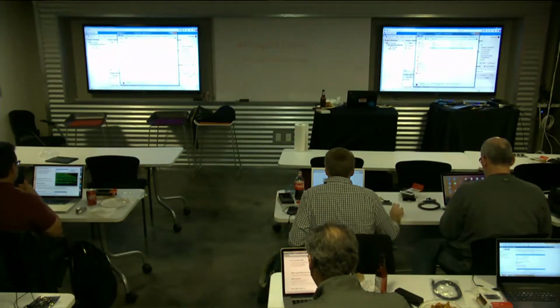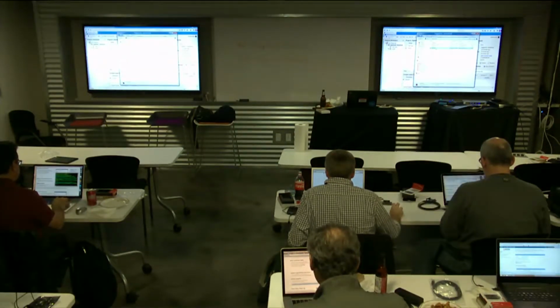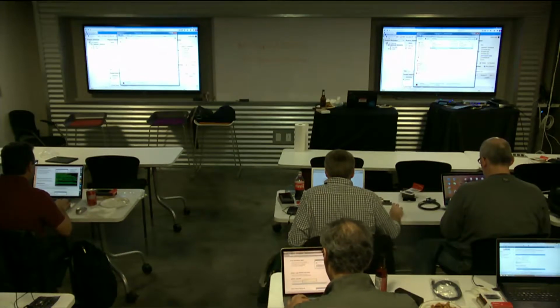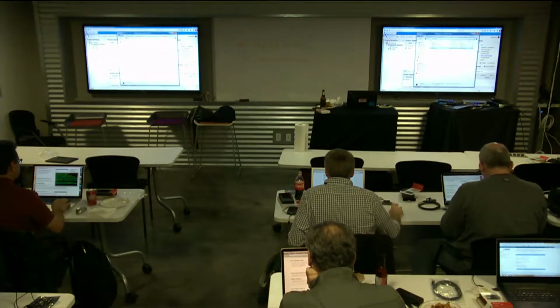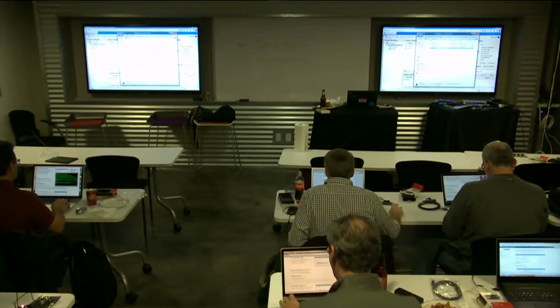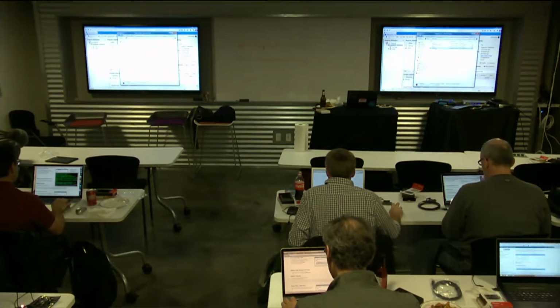Okay. Unknown bootloader. So do an ls on your directory. What we got going on? Well, that's the thing. Oh, there's a slash here, that's why. But did you do the ls to find it? No. Okay, so do ls to see who's there. This is something to do with what I'm mounting, and this is the file. Yeah, you're gonna do a comma though. This is my bin file. Yeah, so you just got the one bootloader. Okay, yeah, so go for that.